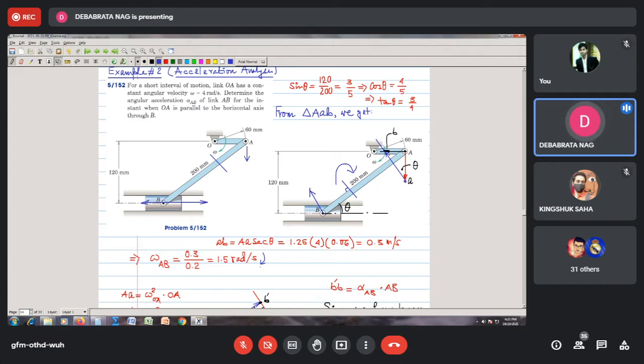The sense is needed because you need to determine the angular acceleration. See the question. Acceleration is never a scalar quantity. So if someone stops at giving only the magnitude, he or she will get 50% of the marks, because the remaining 50% has not been reported. So you have to be very careful. So you see, omega AB is this one.